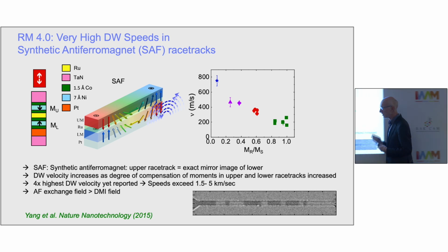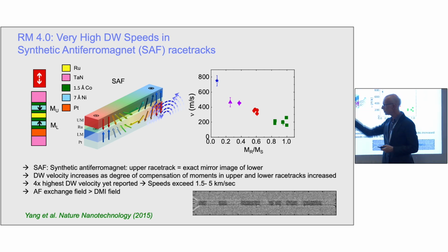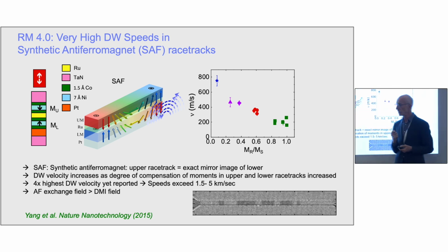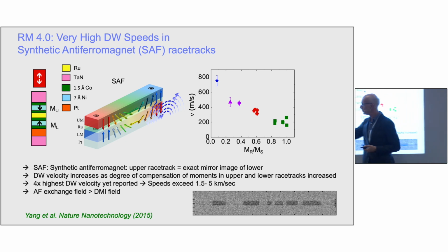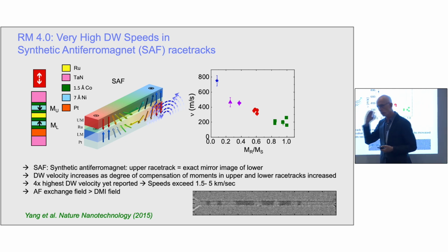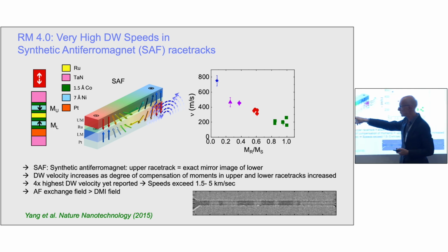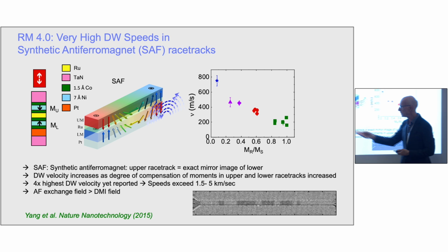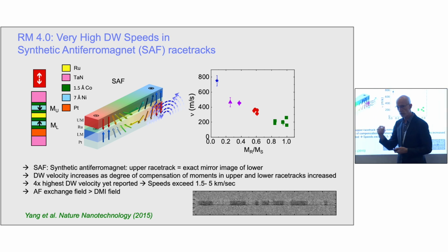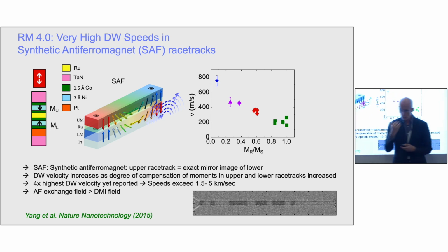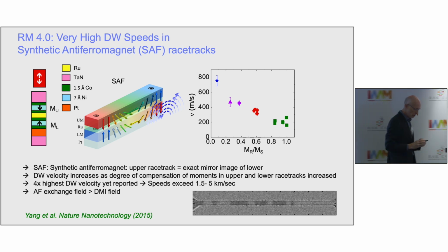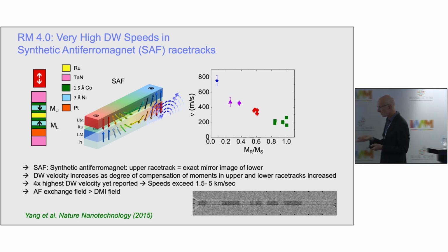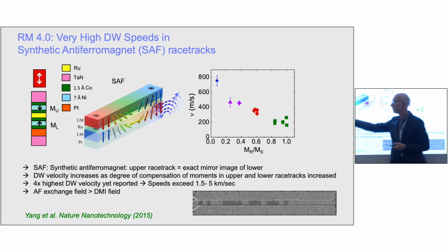So I invented, actually, in 1990, this concept of a synthetic antiferromagnetic racetrack. You simply take 2 magnetic layers, shown here as this red and blue, separated by this, in this case, ultra-thin layer of ruthenium. It's about 7 angstroms thick. It gives rise to a strong antiferromagnetic coupling because ruthenium displays long-range oscillatory spin density waves, which I discovered again in 1990. And this is the fundamental basis.